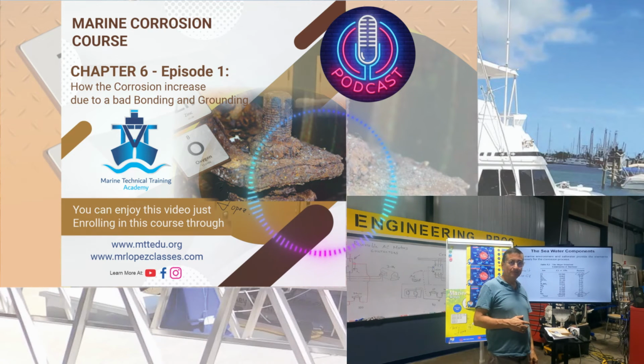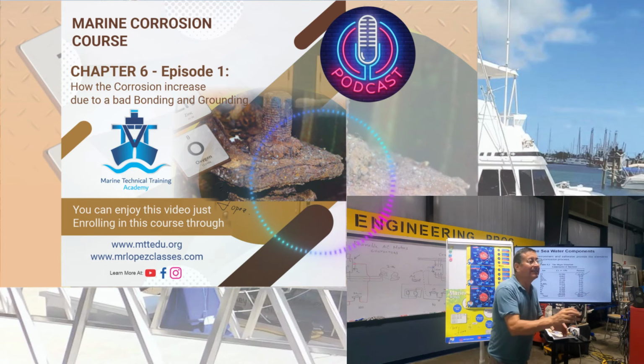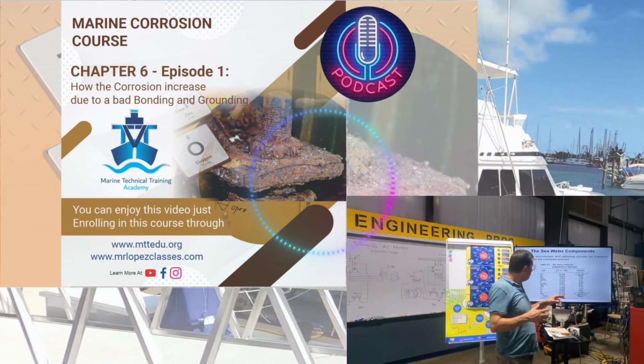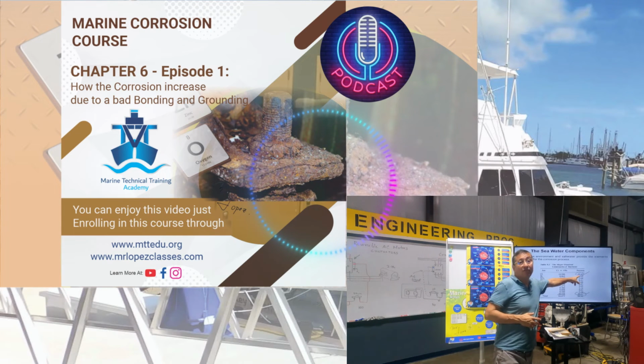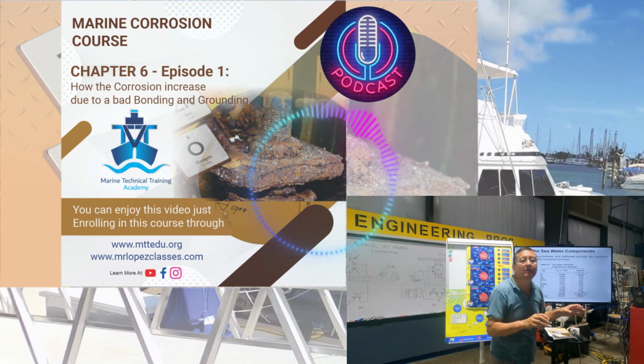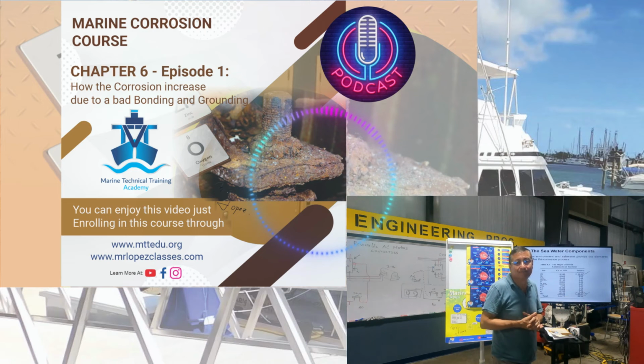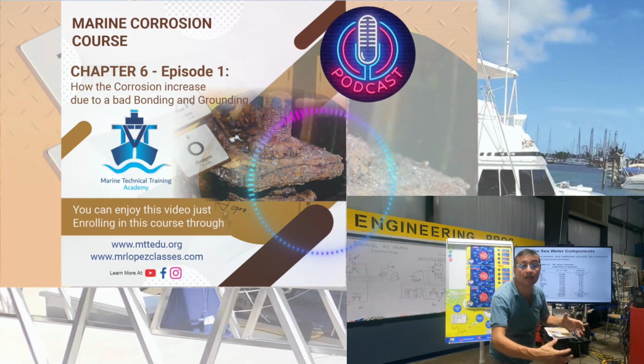Now, 0.1, once again it is rising, 0.2, 0.3, 0.4, 0.5, the voltage is rising, and 0.7, 0.8, and once again 0.9. On both sides it is perfect. That galvanic isolator is working properly. That's the procedure to verify if the galvanic isolator is working or not.